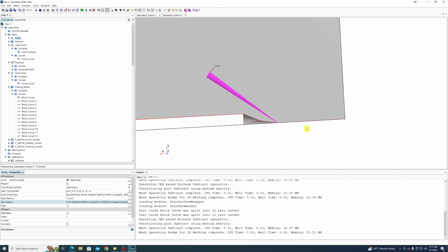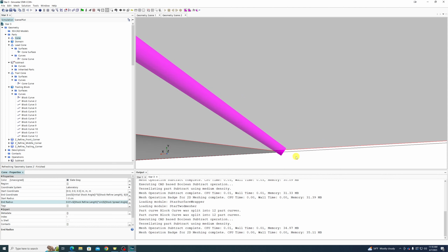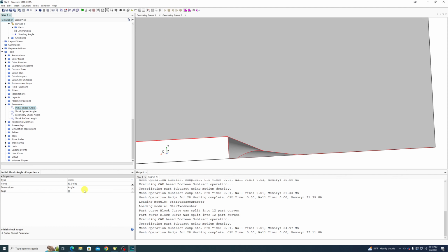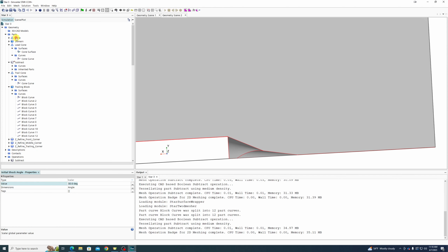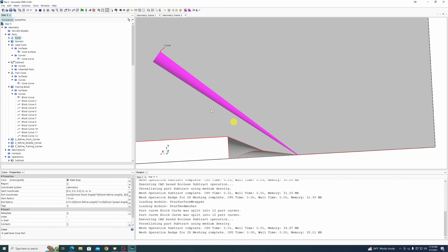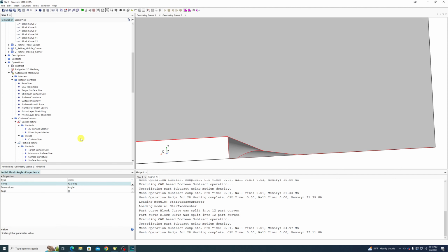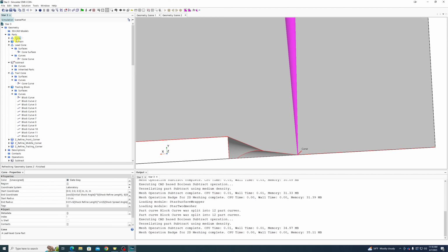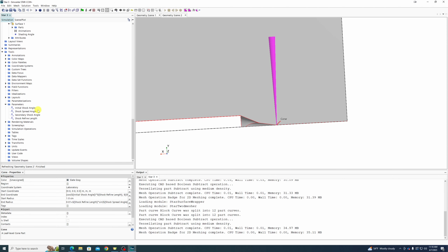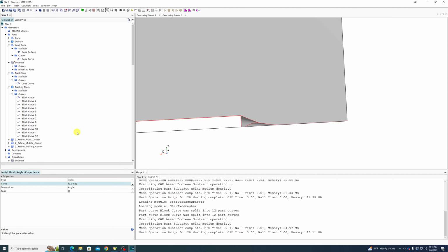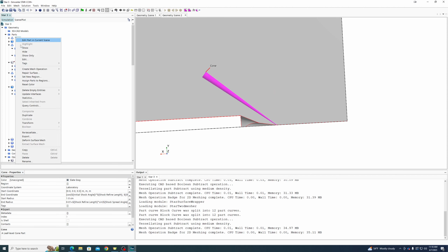So this is our shock wave refinement for our initial one, and you can tune this angle later. So if we wanted to change this initial shock angle, right now this is floating up right there. Kind of get a good mental image of that. Let's just do something ridiculous and say the initial shock angle is 90 degrees. Oh, boom, 90 degrees. So we can just tweak this entire thing because we set up this definition.